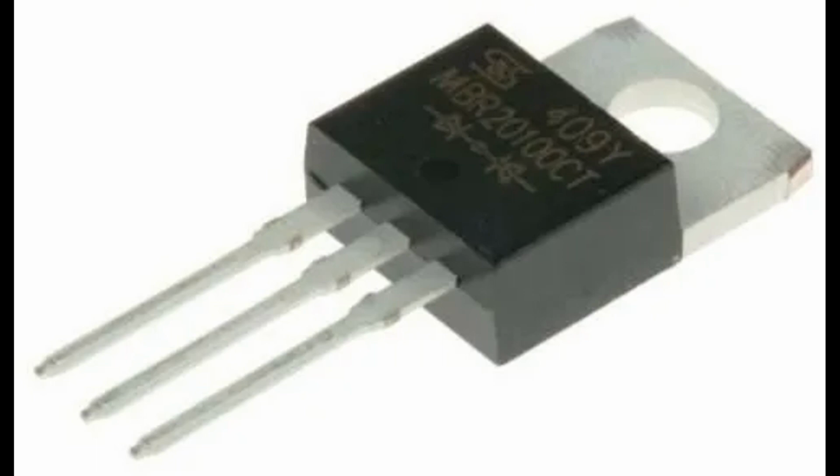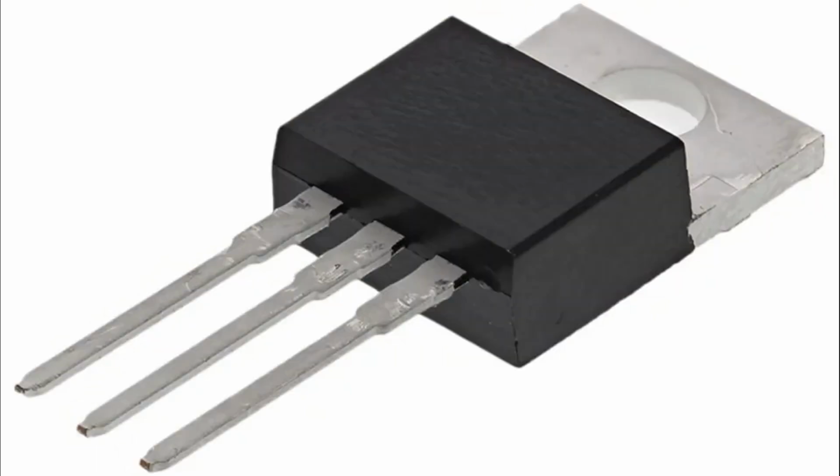Techniques used to achieve low junction capacitance in semiconductor devices include thinner junctions. Reducing the physical dimensions of the p-n junction or gate channel region decreases the total charge storage and lowers capacitance. Specialized semiconductor materials. Using high-quality semiconductor materials with specific doping profiles can help reduce junction capacitance. Optimized device design. Careful device design and layout can minimize parasitic capacitance and optimize the electrical characteristics of the device.